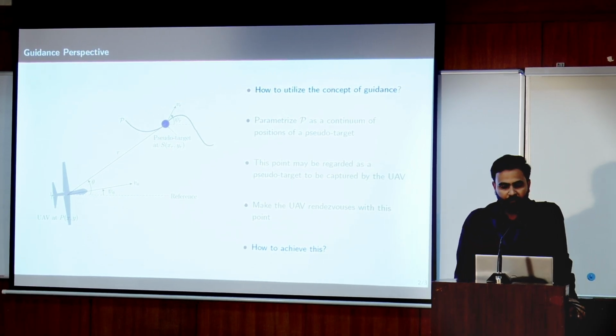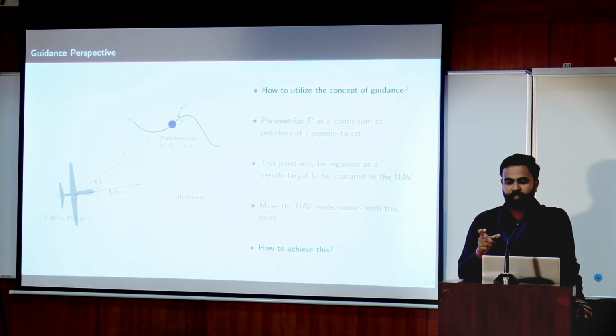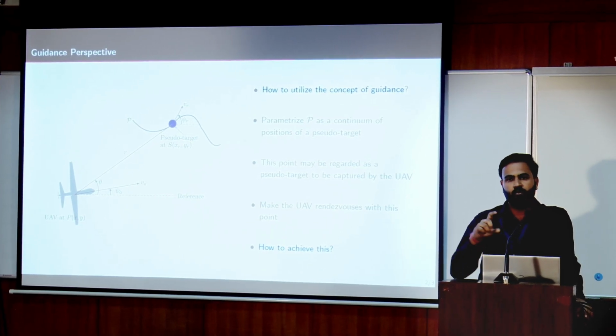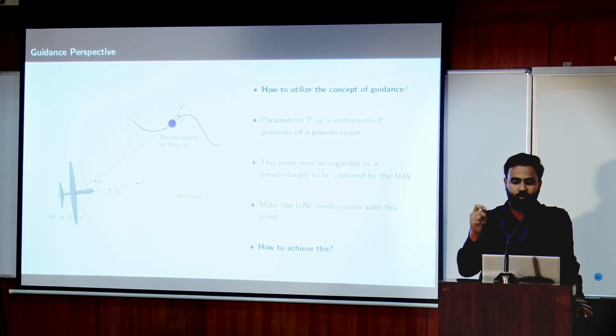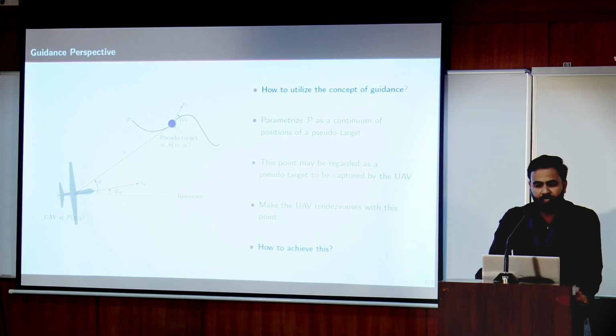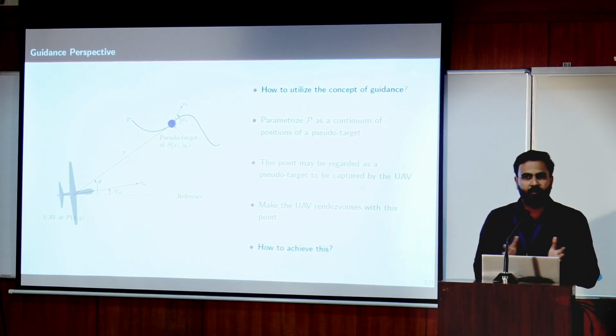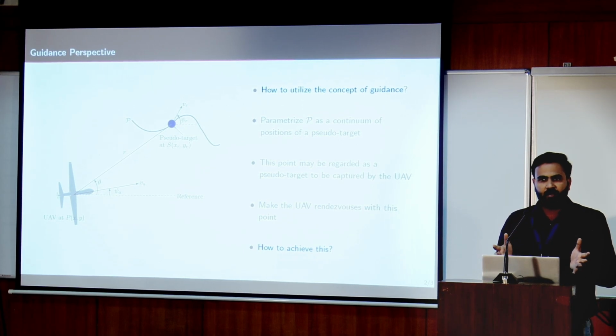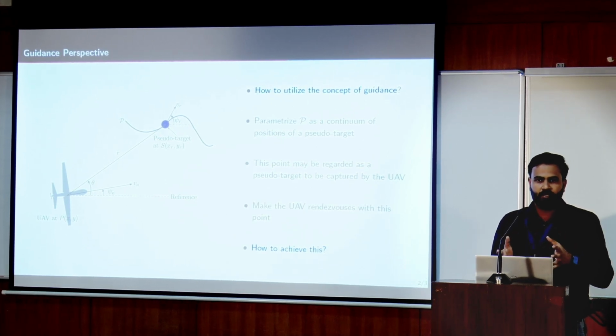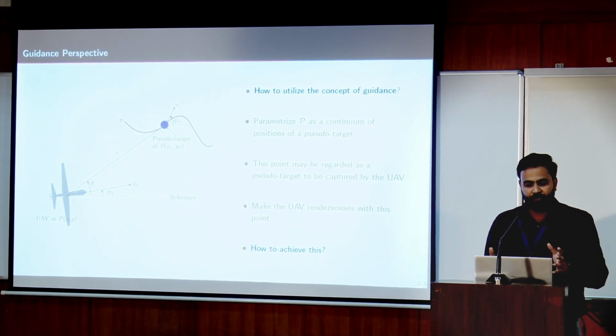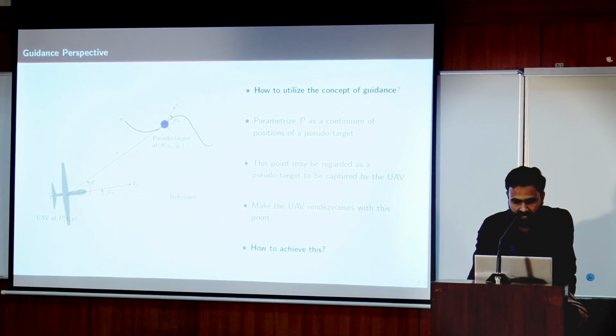So then we came up with an idea after several iterations: if the UAV follows a tail chase motion towards the virtual target, then we can ensure that the UAV will follow any arbitrary path regardless of fast curvature changes. By nullifying the relative separation by following a tail chase, we can always ensure that the moment the relative separation goes to 0, its derivative will also be 0. As a matter of fact, when the UAV converges to the pseudo target, it never leaves it, and thereafter it follows the desired path.